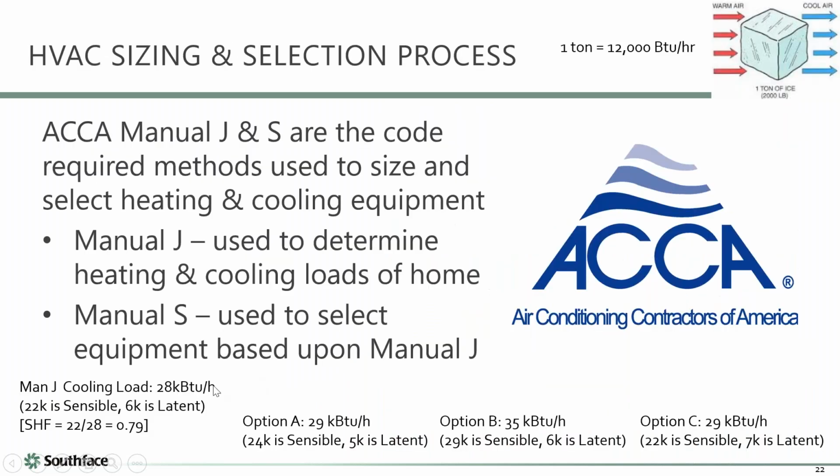So let me go back to this. If you put, let's say, a 4-ton variable speed air conditioner in, 4 tons is way bigger than that. But if that system can throttle down to 2 tons, then I would say that system is fine. A better choice would be a 3-ton unit that would throttle down to say 1.5 or something.